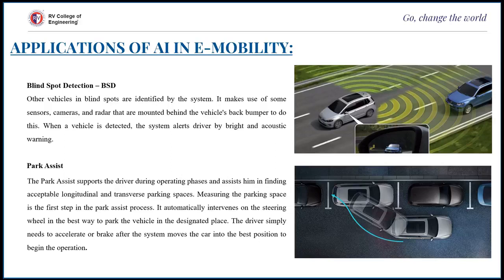Modern automobiles have ultrasonic sensors, which are placed all around the car's exterior so as to determine the parking space precisely, as well as the presence of any obstacles. The control unit will automatically calculate the available space and then build a virtual representation of the area around the vehicle, and then determine the operations which are required for parking. Electrical impulses are also created, which are converted into mechanical impulses that are capable of moving the steering wheel of the car by itself and also carrying out parking operations.